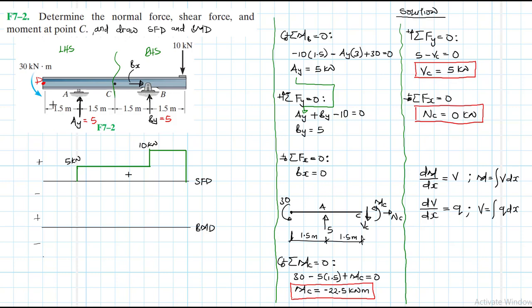So if you were to, and this moment here is negative. All right, this moment is negative. But if you were to make a section, just a very small section here, we have this 30 kilonewtons. Realize that the internal moment that you are going to find there will be in the opposite direction, which is also a 30. And this internal moment is going to be negative. It's a clockwise one, and that is the one that we are going to use when doing the plot.